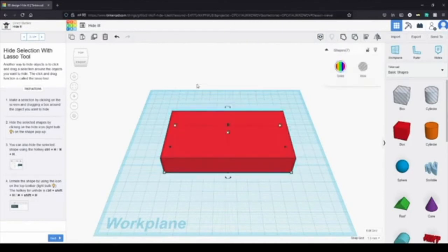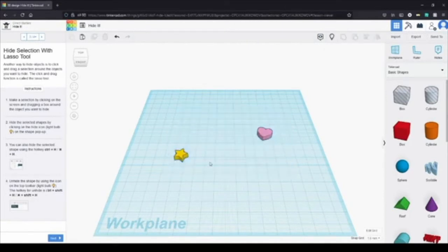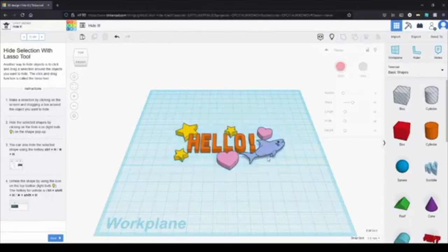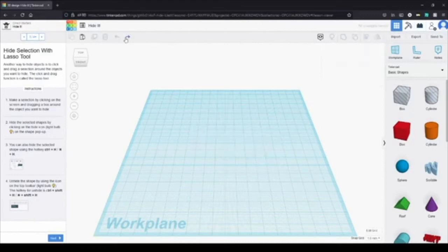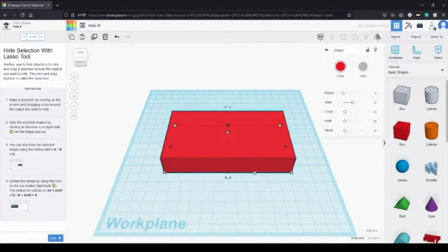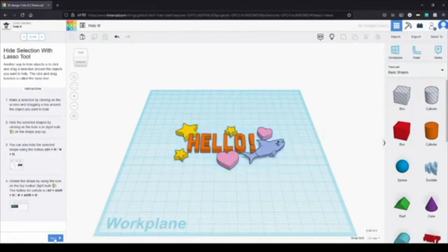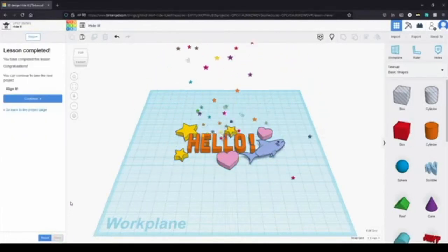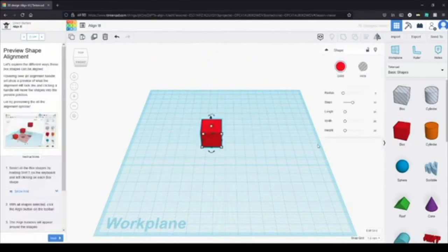So it's going to hide this again. Control H. As you see, some stuff got caught at the bottom. That's okay. It's going to show all. Click this. Control H. And you can just hide any unnecessary things that we don't want. You can always bring that back, and Control H. And that's how you hide objects.